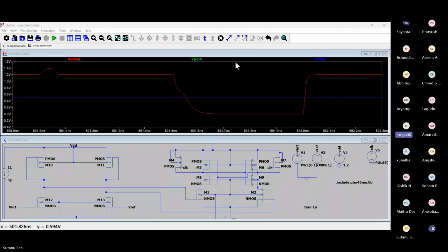So for small signal, for frequency response, you need to write the small signal model. You need to replace all these transistors by their parasitic capacitances and conductances, GM, RO, etc. Get the frequency response. That is true for the first stage. Second stage, it is not operating in small signal model. Therefore, you cannot apply the frequency response analysis here. AC response will not work. Any question before we proceed further?